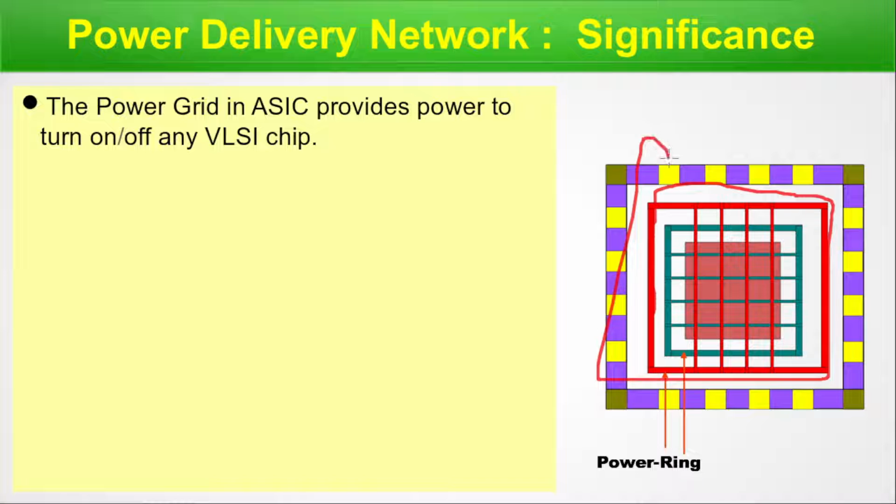This is the thing that we are talking about here, or this one. Now, power strips are the sub lines which take up to the center of the silicon, right? This is a power strip and this is also a power strip. So this is a green color power strip and this is a red color power strip. So one is VDD, another one is VSS.